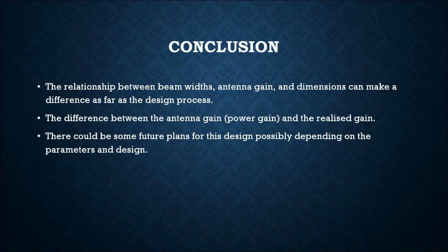Based on the trial simulation results, all of those parameters can be achieved based on the relationship between antenna gain, beam widths, and dimensions, which is the main lesson that I've learned, not only in researching, but also in experimenting in FEKO during my free time. I have learned that higher antenna gain creates narrow beam widths, and lower antenna gain creates wider beam widths, as I mentioned before. The key concept is that the narrower the beam widths, the better the radar and antenna will perform as a best case scenario.